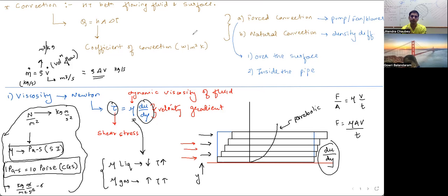Then what about the Rayleigh's number? I don't need to find it separately. Prandtl and Grashof together is nothing but Rayleigh's number. So instead of finding them separately, I can find Rayleigh's number. Yes, if you have Rayleigh's number, you can directly find the Nusselt number.